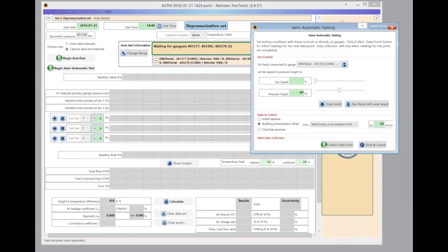So if you happen to be running FanTestic and you decide, aha, I'll open Virtual Gauge to check out my gauge, then it'll close the connections off to FanTestic, and that is a tech support issue that I wanted to bring up because people will be in the middle of the test, they'll open up Virtual Gauge and the whole thing will stop.